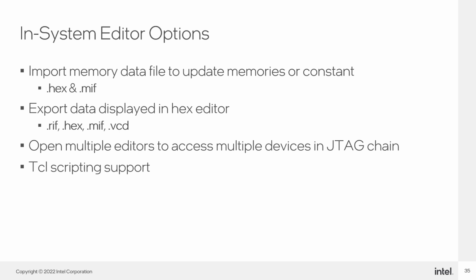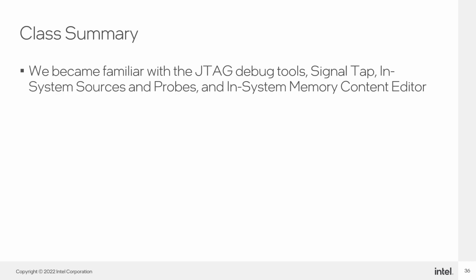You are also not limited to using just a single instance of the In-System Memory Content Editor. You can have multiple editors open accessing different FPGAs in the device chain. To help in automating your testing environment, you can script ISMCE using Tcl. To summarize, I went over the JTAG debug tools that are available in the Intel Quartus software, namely Signal Tap, In-System Sources and Probes, and In-System Memory Content Editor.